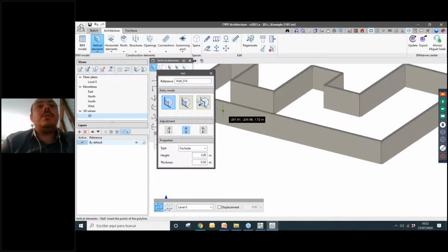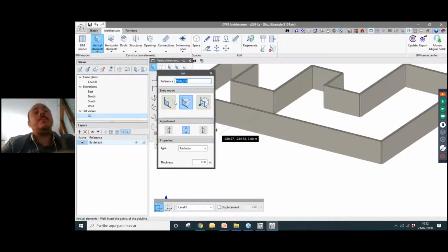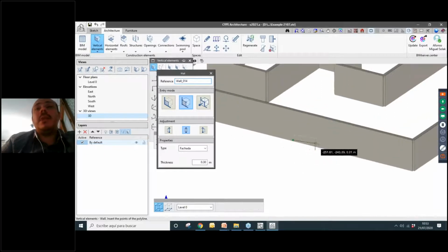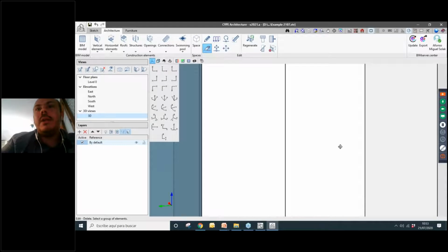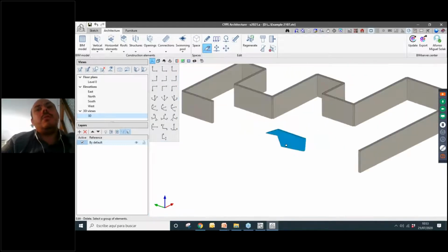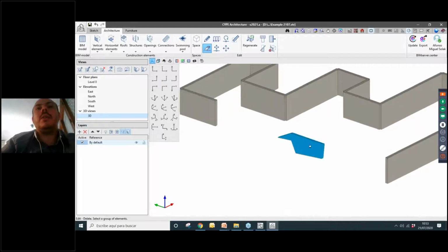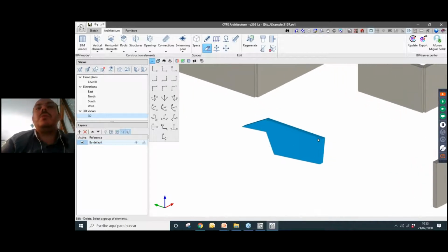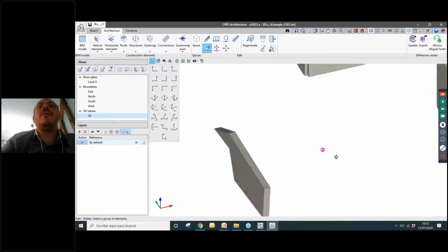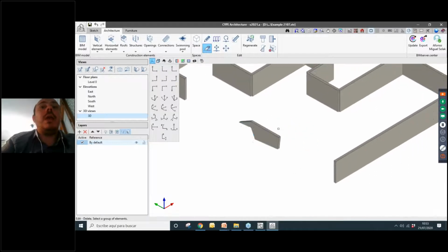Another option would be to generate a wall using some points. In this case, we don't have a height, because here we can create a first point, then a second point, then a third point, fourth point. We can create this wall. Actually, I made it on the same example, so here is the other wall. So we can create it with a geometry that is not exactly a rectangle. We can create a polygon, a regular polygon, to set the geometry of this wall.